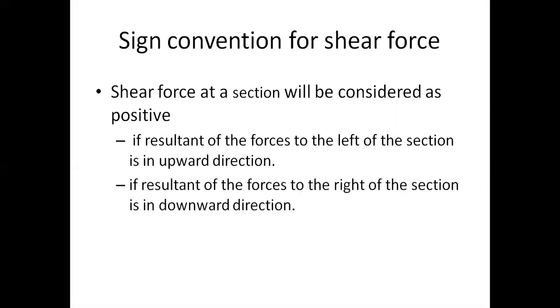Or if you take the resultant force on the right side and it is downward, then it is also positive. So if you take the left side section, it should be upward. If you take the right side section, it should be downward. Then we will take the shear force as positive.